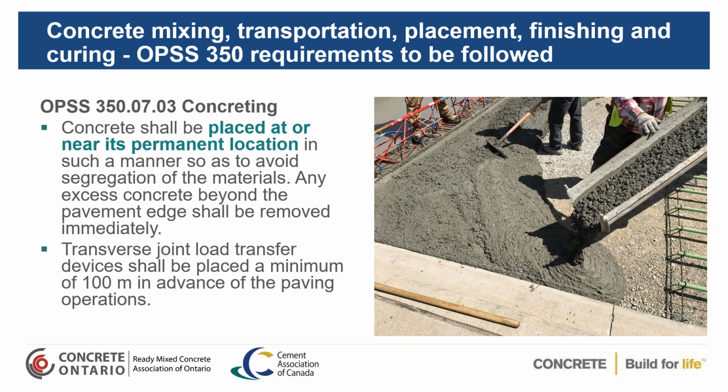Again, when you're looking at the concrete mix for the transportation, placement, finish, and curing, OPSS 1350 has the following requirements. 7.03 actually says it's got to be placed at or near its permanent location. So it's very important that you provide concrete directly to the job site. And also, when you're doing this, you can see that the dowel basket is actually already in place. They're utilizing the ready-mix truck to deliver that concrete, and that will be delivered on top of the dowel baskets as well.